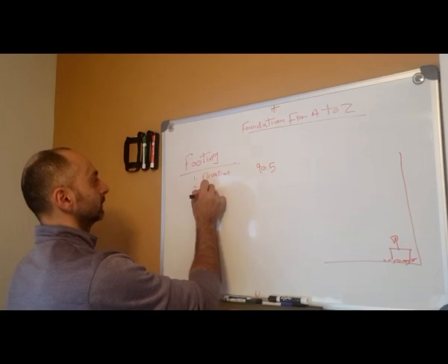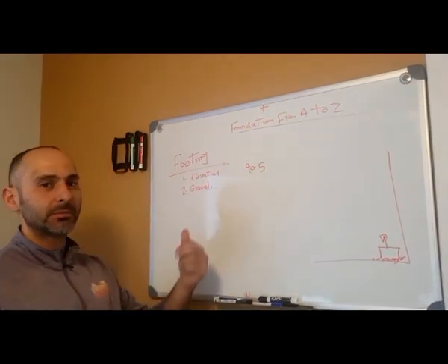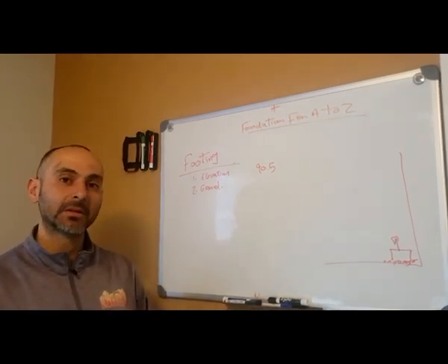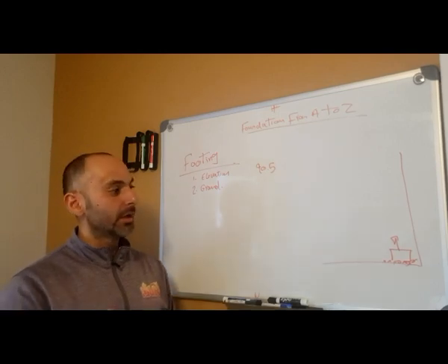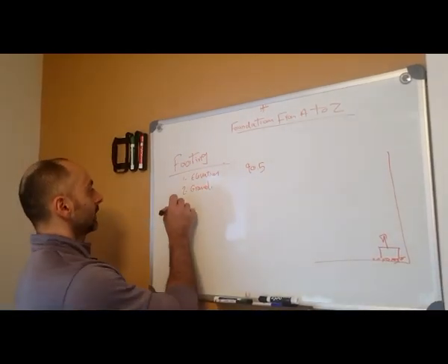Number 2, ground. Inspectors, when they come, this is very important for them. They look for whether you have the ground wire. Make sure you put the clamps, put the wire, your number 4, and make sure it's all ready for inspection.